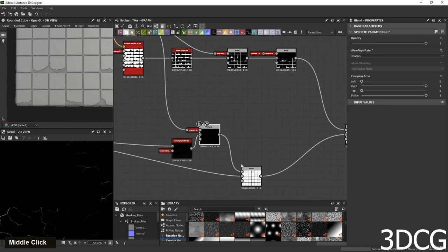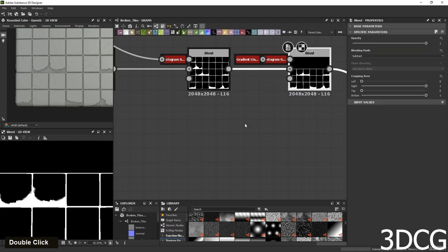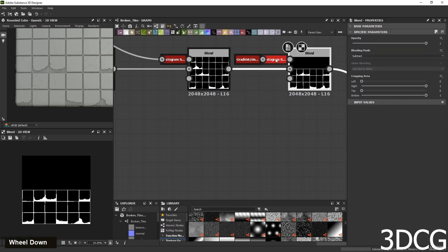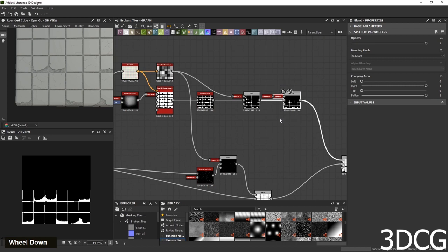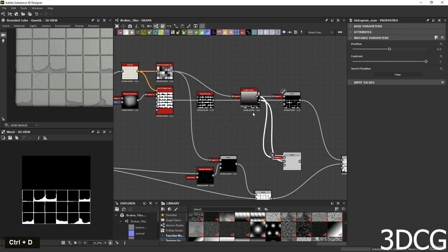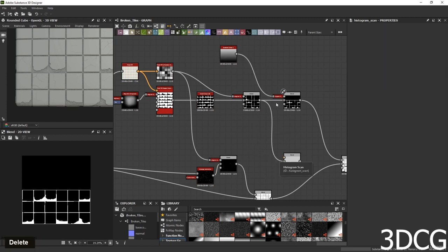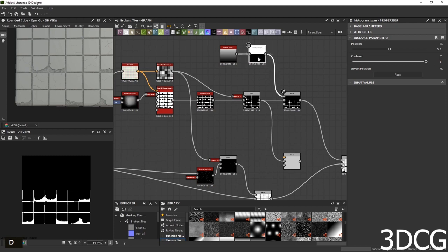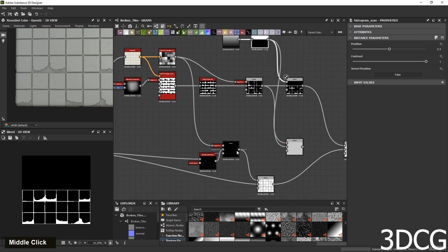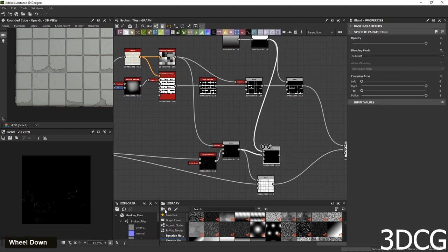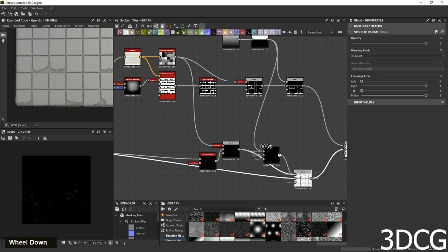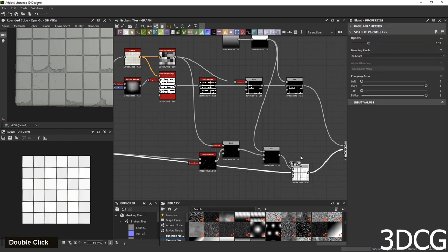All right. If you need to control the crack based on the height, just like we did in here, you need to make the copy of this shape. Let me quickly select this same shape here and also the cracks. Now we have crack only at the bottom. Then connect that to blend.